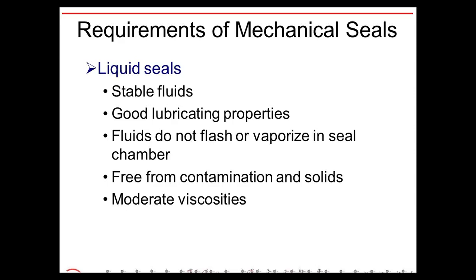With liquid seals, you want to be able to provide the seal with a stable fluid, a fluid that has good lubricating properties, fluids that won't flash in the seal chamber, fluids that are free from contamination and solids, and ones that have moderate viscosities.